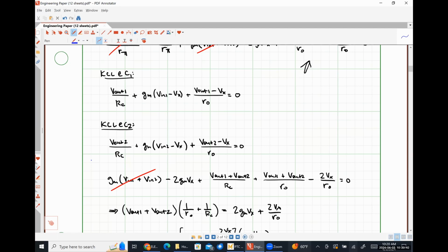In a sense, what we did here is the exact same thing as what we do when we're doing KCL at a supernode. There's no voltage source or anything, but we're just saying, I'm doing KCL over here and KCL over there and adding those results together, which is exactly how KCL worked at a supernode way back from circuit one.